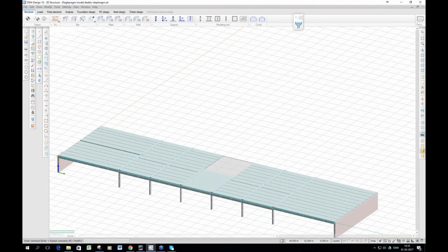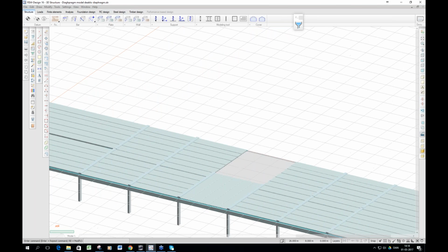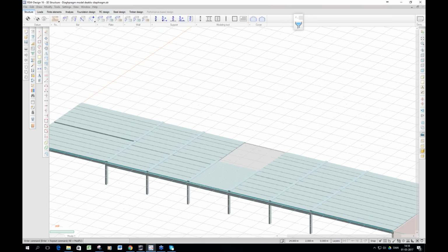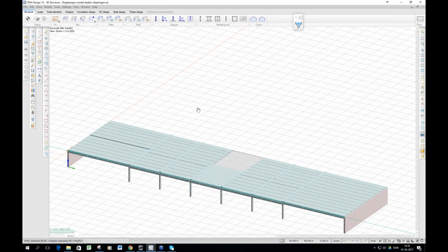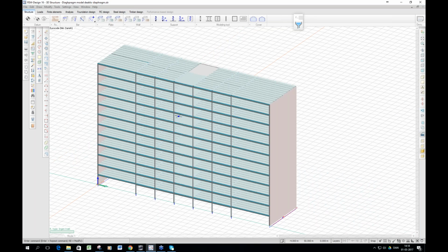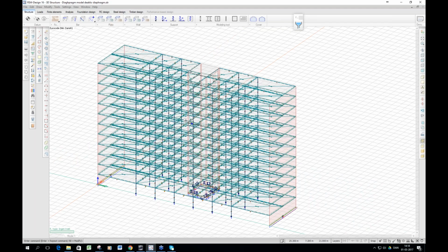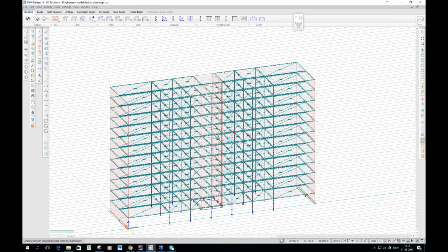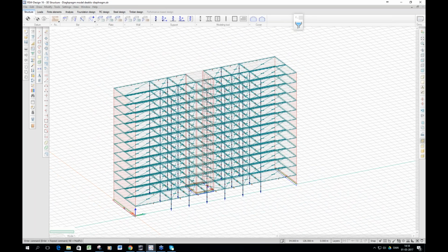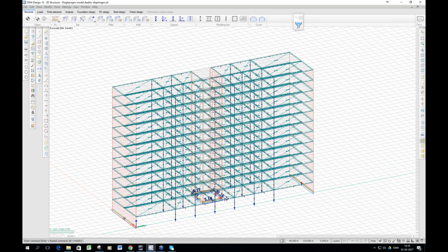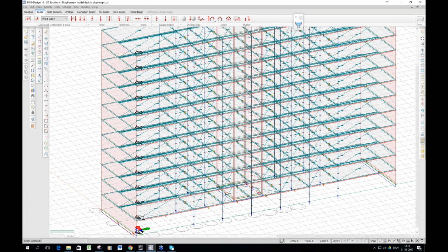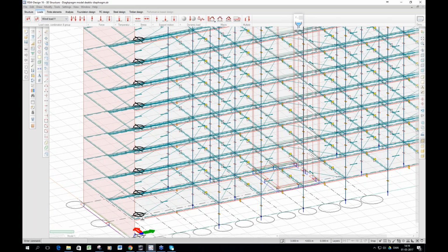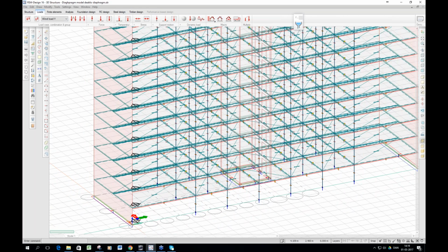If you see, the hollow core spans are like this, and the full building like this. So, a combined beam, column, wall, plate building, a normal building. As loads, I have added 3 kilonewtons per meter as line load on the edge of the slab.